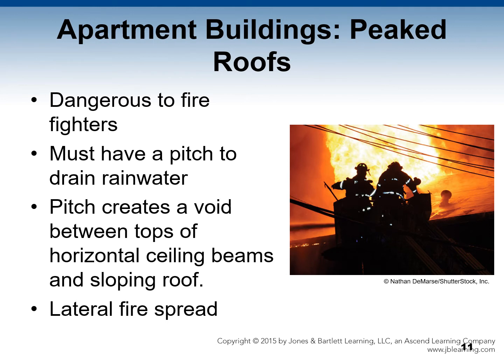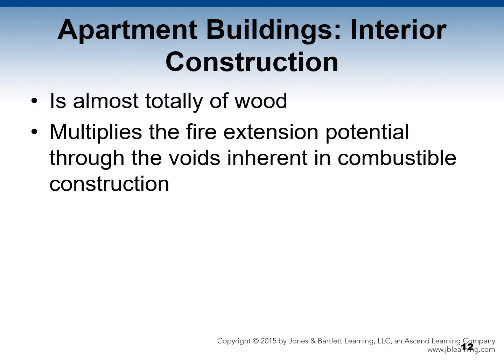There are very often peaked roofs, particularly in northern latitudes where you have snowfall involved. These are dangerous to firefighters, and they must have a pitch to drain rainwater or snow. But the pitch creates a void between the tops of the horizontal ceiling beams and the sloping roof, and fire can spread laterally through this space. With interior construction, it's usually almost totally wood, and this multiplies the fire extension potential through the voids inherent in combustible construction.